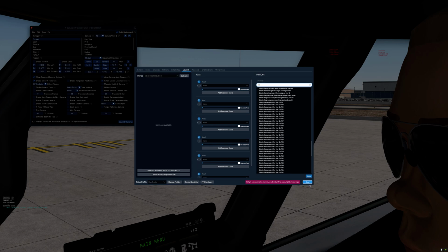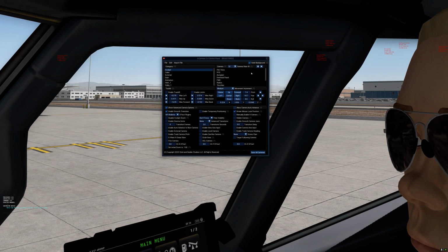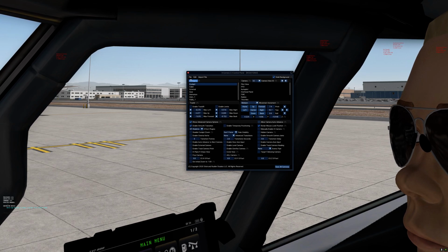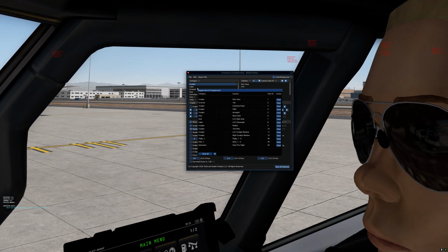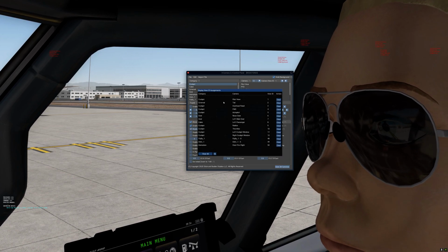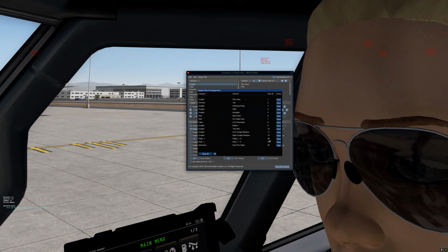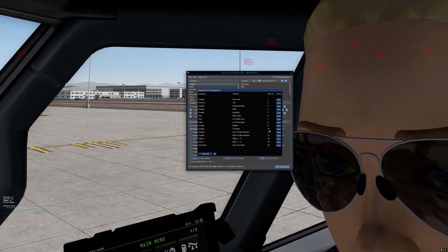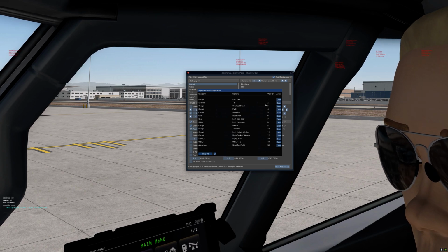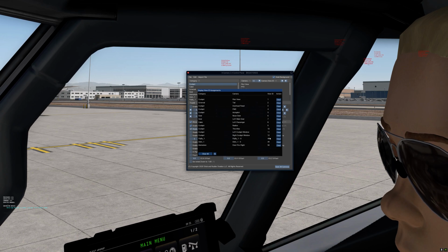Now, the way you can check to make sure you're using all your buttons, but you're not overlapping a function, is to go to Control Panel, File, Display View ID Assignments, and here you can see everything that's assigned. What you want to do is look for all 20 of your buttons. It's nice if you have them in numerical order here. They don't have to be. Here I have 1, 2, 3, 4, 5, 6, 7, 8, 9, 10, 11, 12.